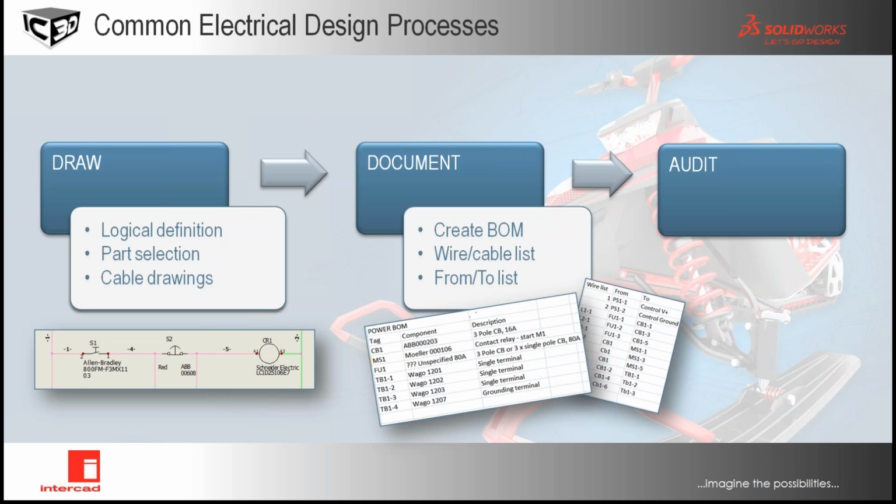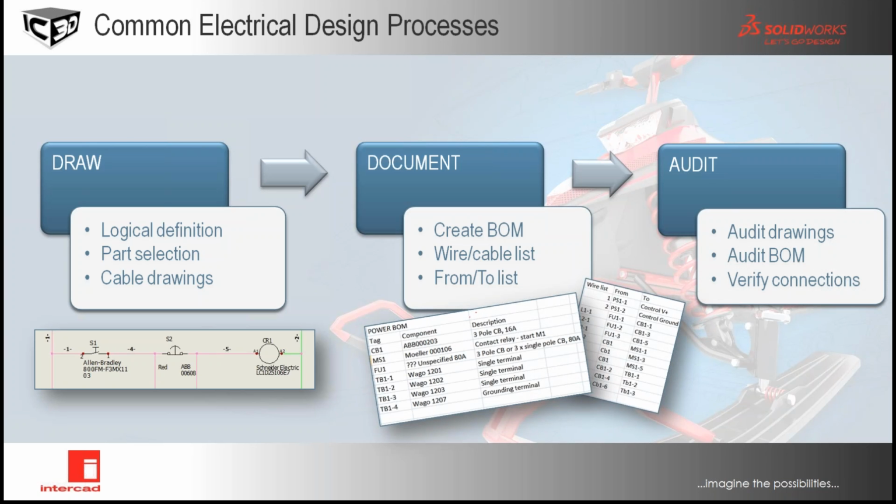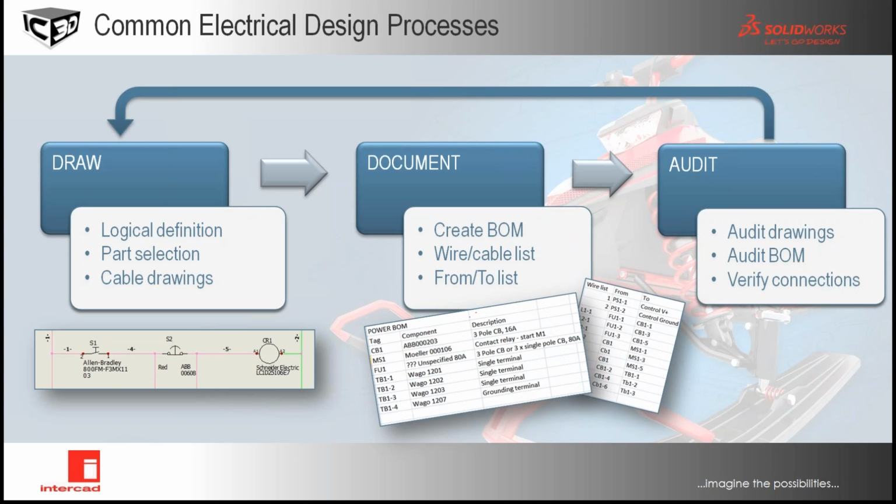And then obviously you've got to make sure that what's in your cable schedule, for example, is 100% accurate as per your drawing. Now, if something does get modified or changed, then the whole process gets repeated again. You change the name of the circuit breaker, then obviously the wiring list needs to be updated, and so on. So other documents need to be updated, and if it's a manual process, then it takes a lot of time. I'm telling you that from my own personal experience as well.